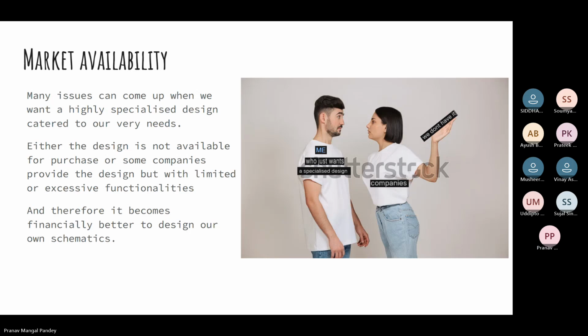तो excess voltage हो गया, उससे बचाता है. Excess current हो, उससे भी कहीं कहीं handle करता है. There are different ways, ठीक है? And a normal diode normally बस gives a way for current in a single direction. So normally we use, like, normal diode और Zener diode का यही difference होता है, ठीक है?